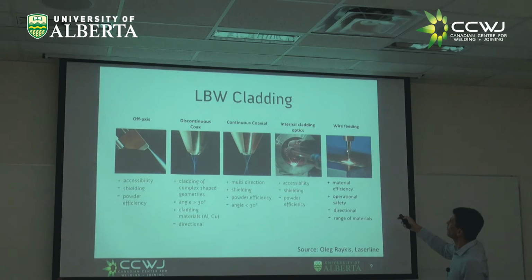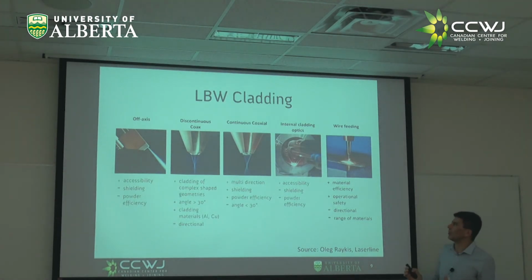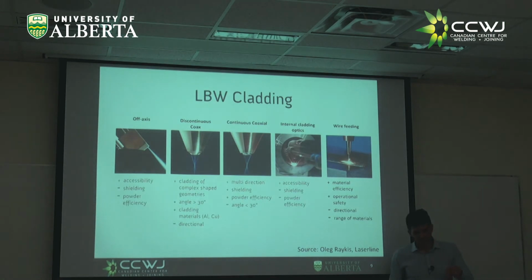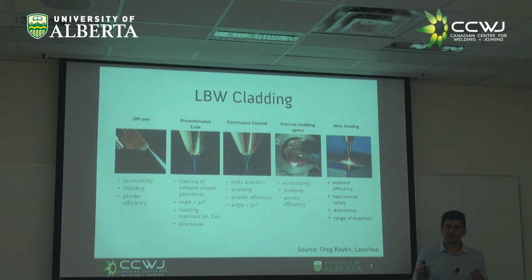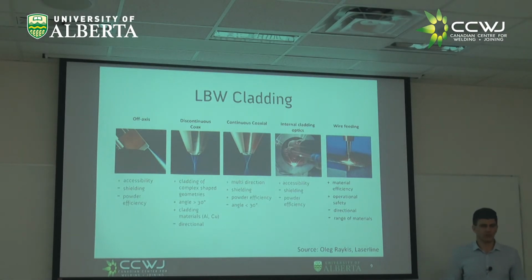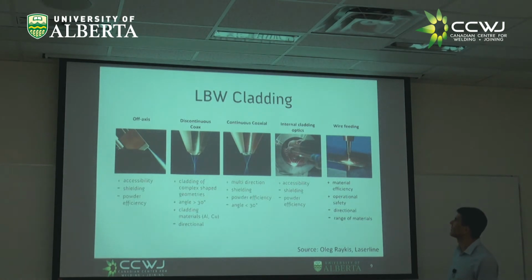And here you have the case of wire feeding. You can put the wire and the lasers in many ways, right? Often the laser comes perpendicular to the workpiece and the wire comes from the side. There are some optics for making coaxial wire feeding. They're still experimental, and very expensive. I'd like to have one of those. There would be so many things that we could do with coaxial optics for laser with wire.